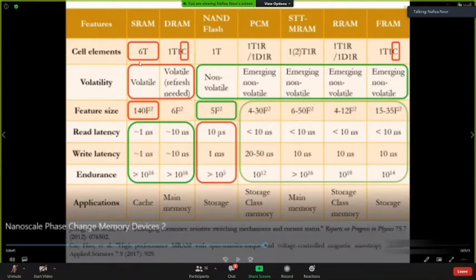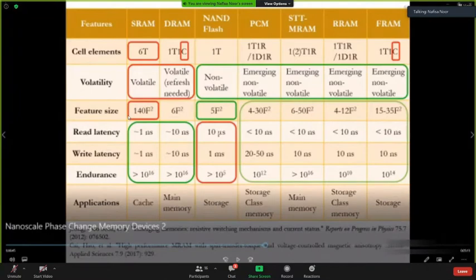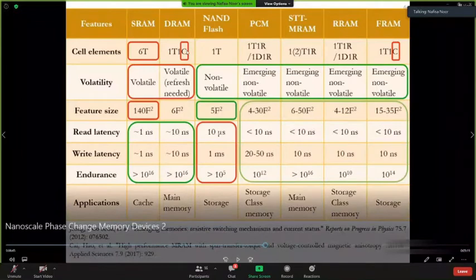So first of all, the SRAM has 6 transistors, so it has a very large feature size. If you think about some new memory, then we would try to get one that doesn't have the problems that are highlighted as the red here. So we don't want to get a large memory structure. That's why we'll not try to get so many transistors or the back-to-back connected inverter. Also, having the capacitor is a problem. That's what I have already mentioned, because if you have a capacitor, it is really difficult to scale it down.